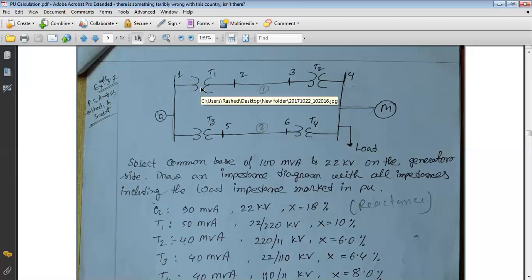After getting the high voltage, the secondary portion of the transformer is connected to the other transformer, called transformer 2, and this connection is a transmission line actually. So this is the transmission line, and this should be a high voltage transmission line, because if the generation is 33 kV and this transformer steps up the voltage from 33 to 132 kV, this line is the high voltage transmission line, because now 132 kV is transmitted through this line.